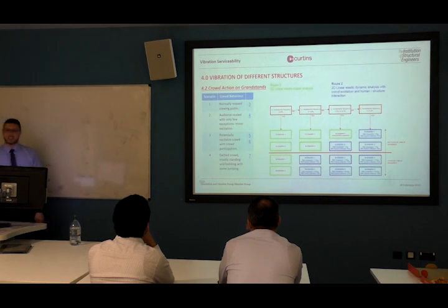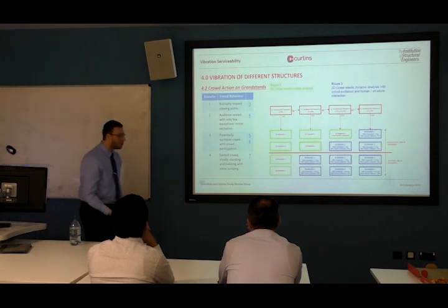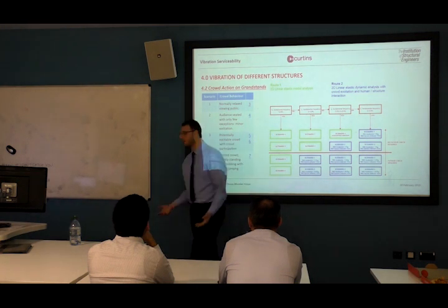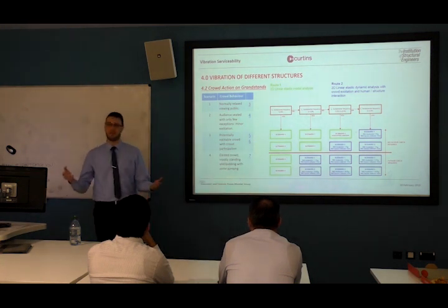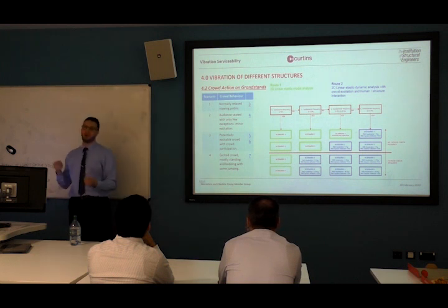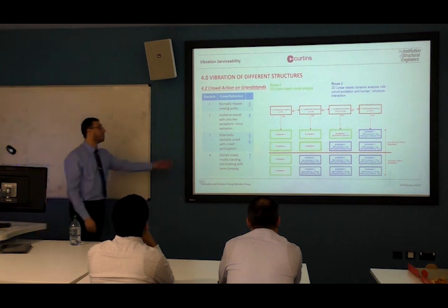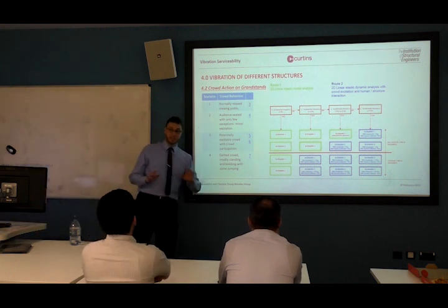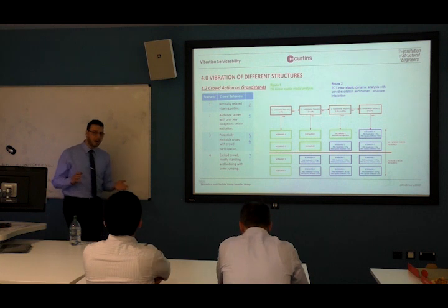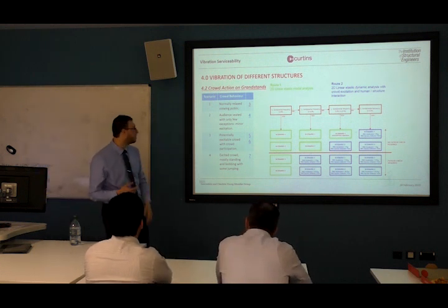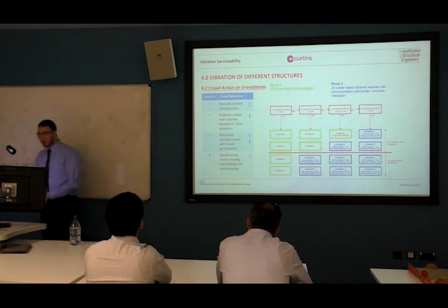So this is if you're hosting someone who's from the 60s, the 50s maybe, and all the crowd is elderly people. You're not expecting them to come and jump and bob. They're not going to cause any problem to the structure. But the second scenario: the audience are seated, but there are some people jumping, some people making some noise, but not a lot.